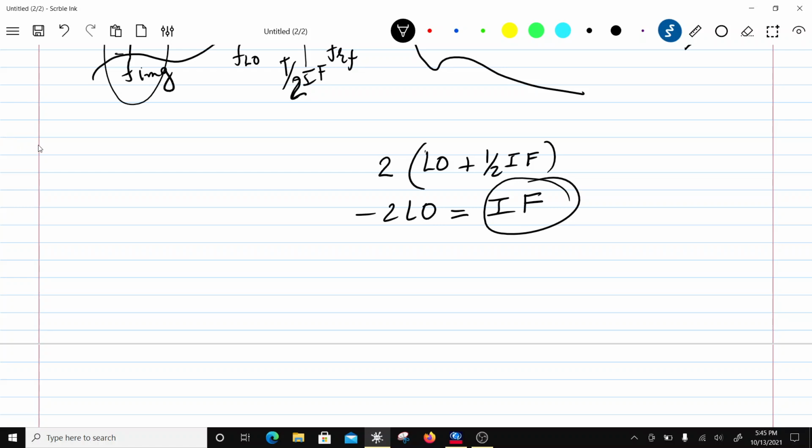Now this problem is severe with half IF. With 1/3 IF, it also exists, but it is not that severe because 1/3 IF is closer to LO, much farther away from RF, and the filter skirts are going to take care of that, right? So the worst scenario is the half IF situation, and that is why the SOI of a receiver is more important than the TOI.